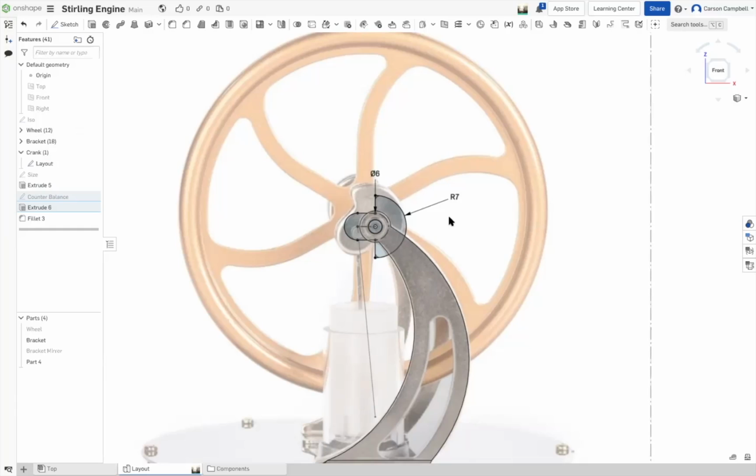Most of the print shops will create that sizing for you. There are instances where you will scale the whole model, and an injection molded part is definitely that. They have to make the mold 2% bigger because when plastic melts, it shrinks by 2%. So this is not a good example of doing a global scale.